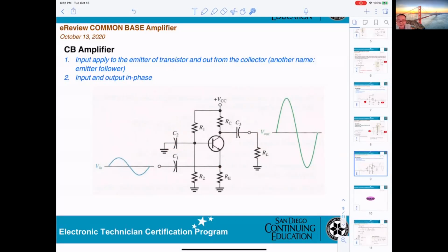If I don't say anything, that means it looks like it's not correct. Coupling? DC blocking. They say blocking. Now I'm asking you one thing. If the capacitor C2 is shorted, what happened? The base is 0. So the voltage at the base, no matter DC or AC, will be 0. They short to the right.